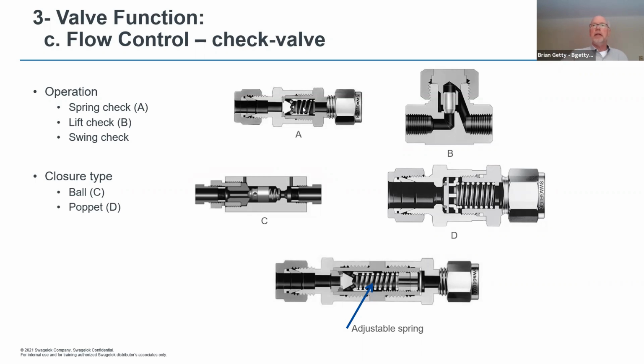They had to clean these things out frequently. It was creating a bit of a problem. I went in and had a look at their application, and once I saw just how much fiber there was in the water, I made the suggestion that we go to something like this, which is a lift check valve. As soon as you have pressure here, it pushes up, because this is only held in place with gravity. It would push out of the way, and you get a flow through. If there was a back pressure, because it's gravity, as soon as you cut the pressure, this poppet would close automatically. On top of that, adding back pressure creates an even better seal, because the back pressure would come up here, push down, and create an even better seal.